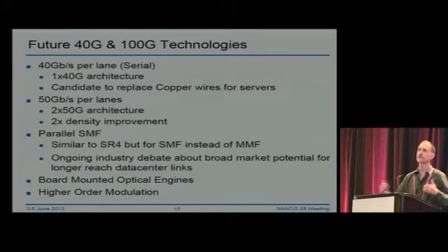If you're going 500 meters or 1 kilometer, is it okay for you to have anything other than duplex single mode? And in the Q&A, if there's a little bit of time, I'm actually going to ask maybe for audience reaction if the moderator allows me. But very, very big debate in the IEEE. The other major shift is board-mounted optical engines, so actually moving away from the pluggable module paradigm, and then higher order modulation. And I'll go into the last two in a little bit more detail.